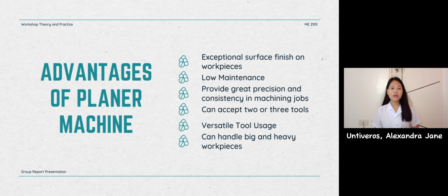And of course, the planer machine has its own advantages and disadvantages. For its advantages, it provides exceptional surface finish on workpieces. It is also low maintenance, provides great precision and consistency in machining jobs, can accept two or three tools, has versatile tool usage, and of course can handle big and heavy workpieces.